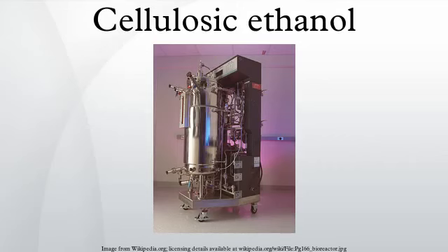As mentioned, a significant obstacle to the dilute acid process is that the hydrolysis is so harsh that toxic degradation products are produced that can interfere with fermentation. BlueFire Renewables uses concentrated acid because it does not produce nearly as many fermentation inhibitors, but the acid must be separated from the sugar stream for recycle, simulated moving bed chromatographic separation, for example, to be commercially attractive.